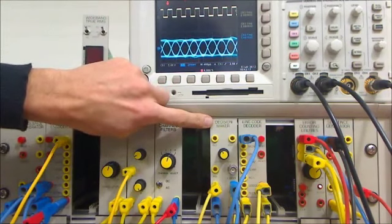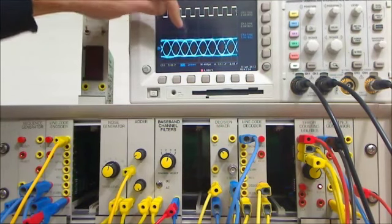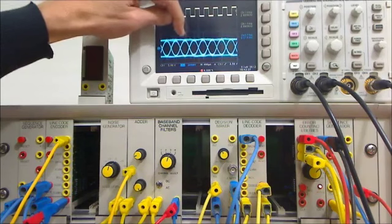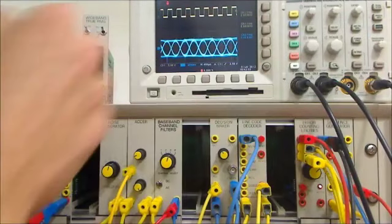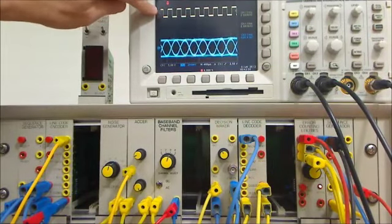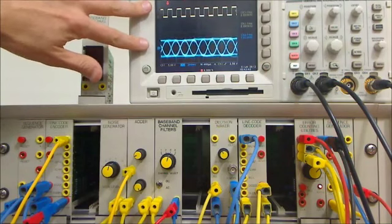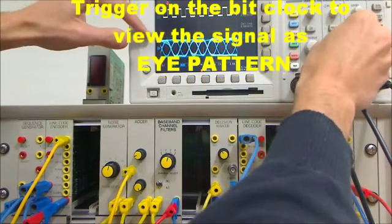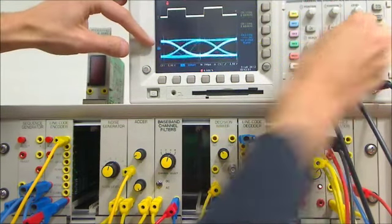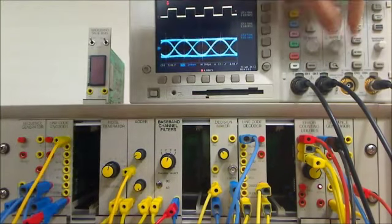The decision maker is the front end of the receiver, and its purpose is to sample the received signal at the correct instant so as to be able to make decisions as to what the level of the signal is at that instant. Because we're triggering our scope on the bit clock, we can easily view the eye pattern at the receiver. I'm just using 2 channels of this 4-channel scope to emulate a 2-channel scope. Changing the time base, we can have a good look at the eye with a little bit of background ambient noise from the noise generator.